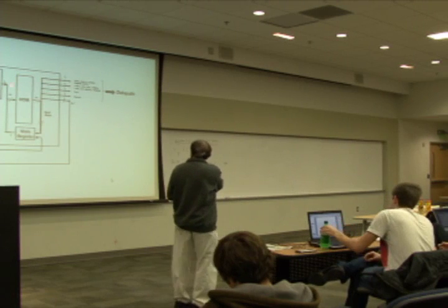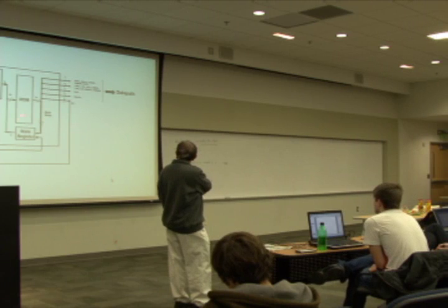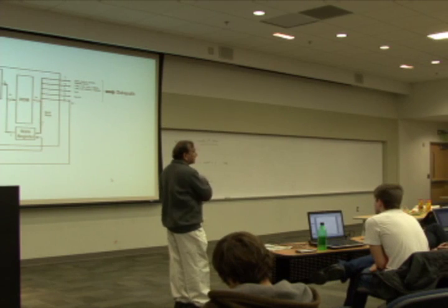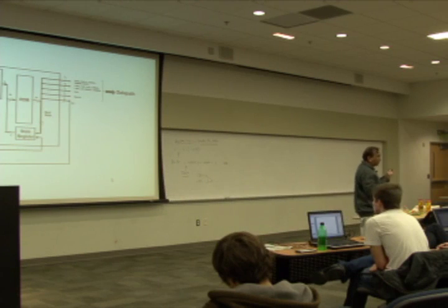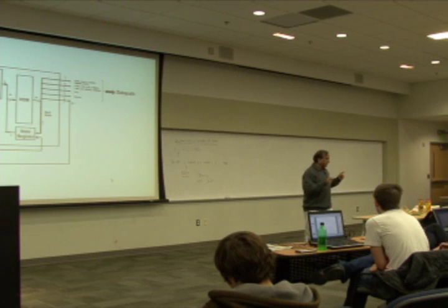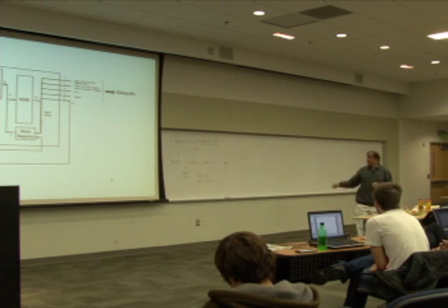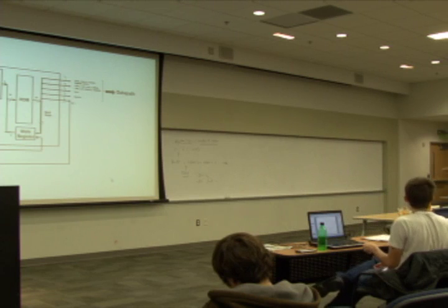On the other hand, if you look at this design, the microprogram design, the nice thing is if there is a flaw, then it is just a particular line or a location in your micro ROM that happens to have the wrong selection of bits. You can go and modify that, right? And so you can reprogram the ROM in order to correct any design flaws. Whereas in this case, it is harder to do, and that's why it's called hardwired design, and this is called microprogram design.